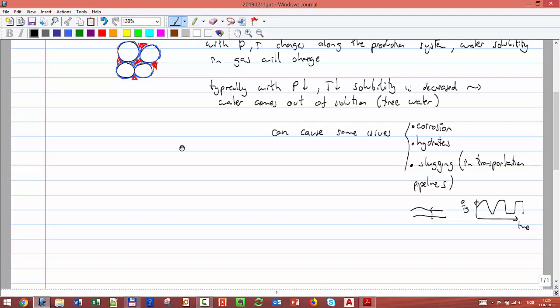That is caused partly because in some positions in the pipe, if you have liquid, if you have this water coming out of solution, it's going to block the pipe. Okay, in some places, and then the gas who is in the back is going to push, increase the pressure, and flushes the gas out, and then the process is repeated. The liquid is accumulated, the gas is pushing, and then you get a profile like that.